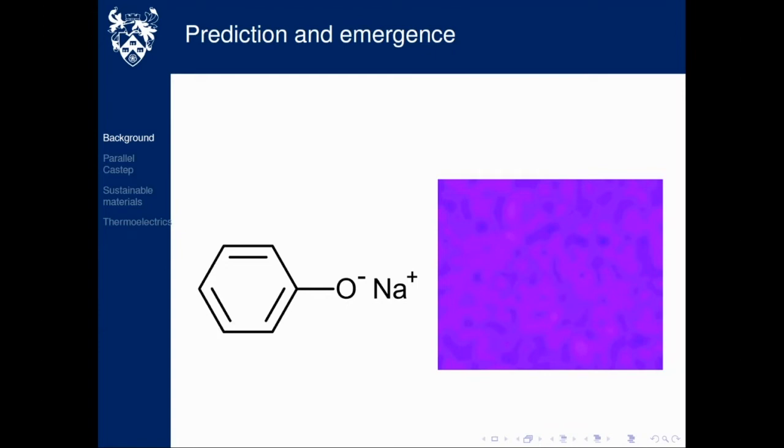So I've run CASTEP on that. CASTEP works iteratively, we'll talk about that in a few moments, but I've plotted the electron density in a 2D slice straight through the middle of this molecule, iteration by iteration. I've deliberately messed with CASTEP's code to take a really stupid initial distribution of the electrons, which is what I'm plotting on the right hand side here. I've basically given a uniform random distribution of electrons throughout a box in space, which is terrible. We don't normally do that, but just to illustrate it.